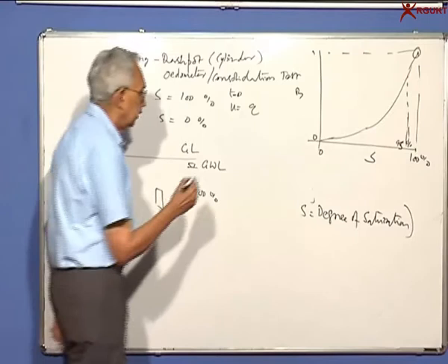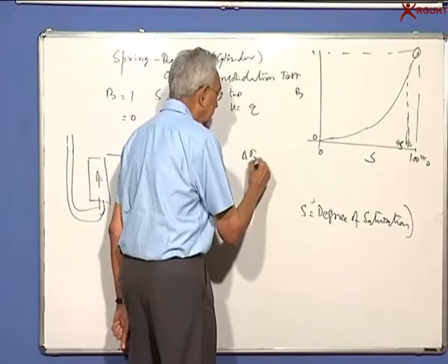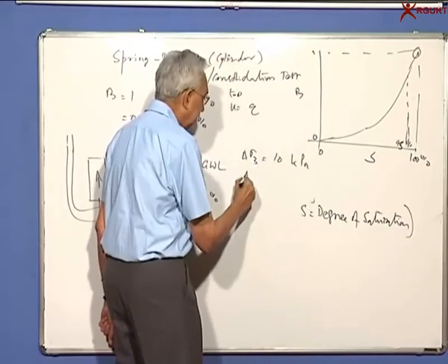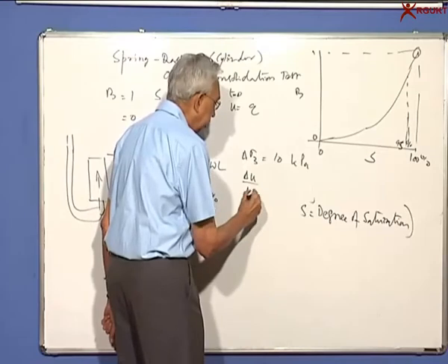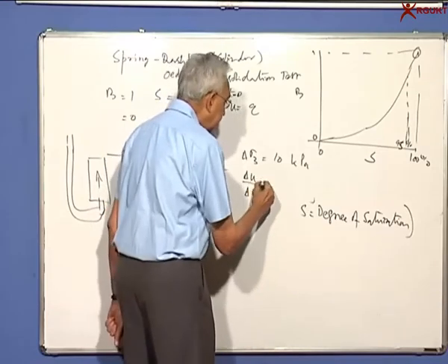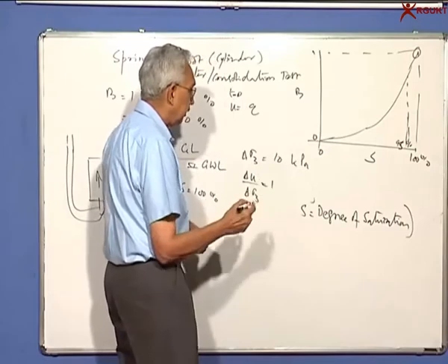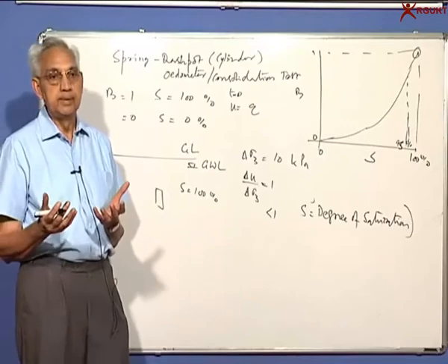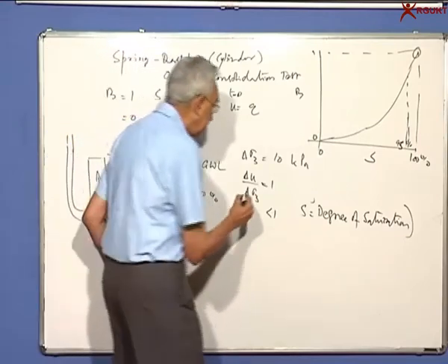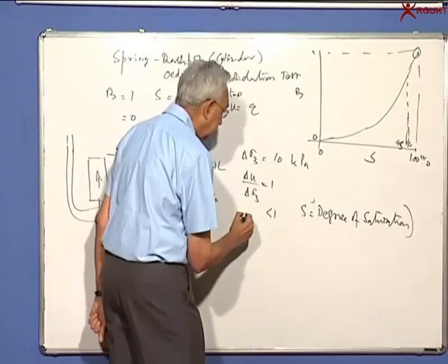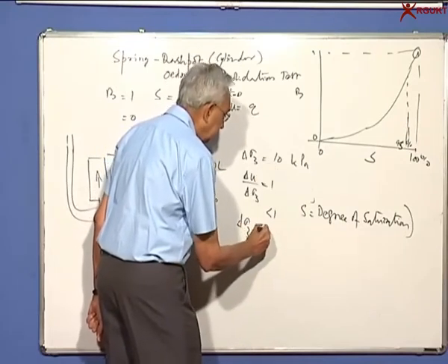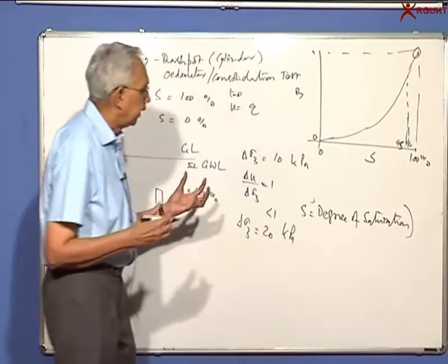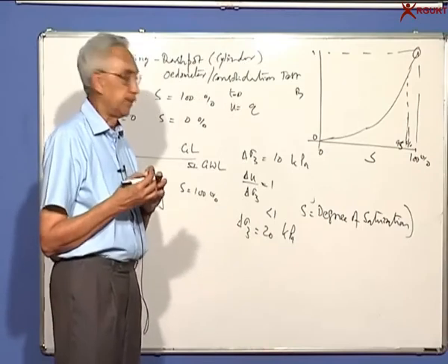How do I check? I apply delta sigma 3 equal to 10 kPa. Then I measure delta U, and I find delta U by delta sigma 3. If it is equal to 1, we are good, because the sample is saturated. If it is less than 1, it means the soil is not saturated. Then I increase the stress, adding another 10 to make it 20 kPa. So I keep applying pressure and make sure the air in the voids gets compressed.